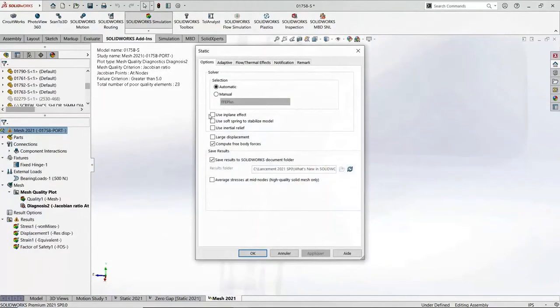Other performance-related enhancements to solvers have been implemented in SolidWorks 2021. The FFE Plus solver can solve contacts faster thanks to the multi-core support, just like what the other solvers can already do. The Intel Direct Sparse solver can handle larger studies, even problems with more than 4 million degrees of freedom.